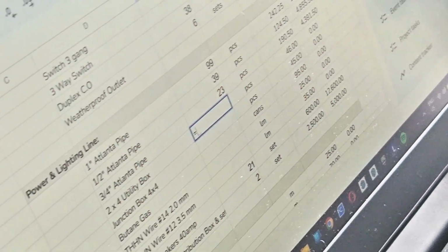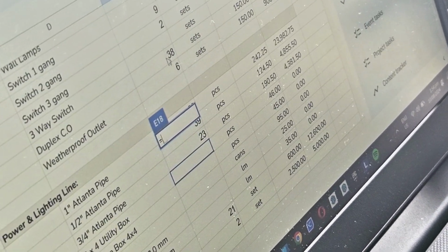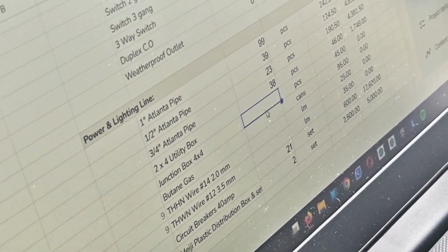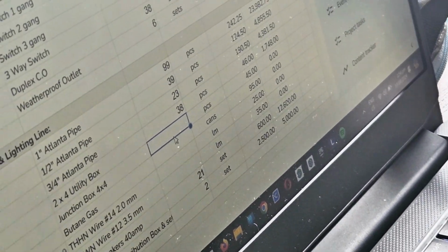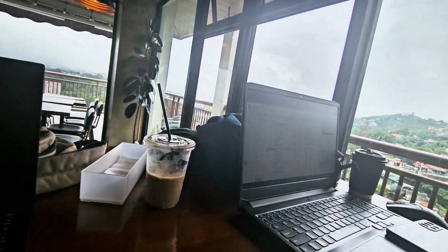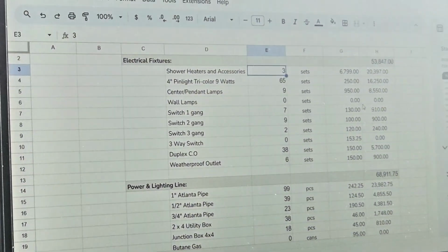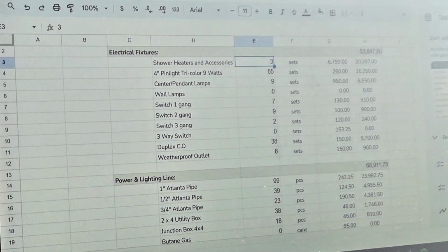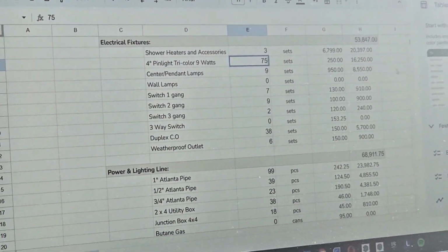And then look for the total number of outlets up there, which looks like CO. There, equal, yes, enter. As you need. But even your switches actually need a utility box. So plus number of switches. So you can assume 1 or 2 junction boxes per area. Center and pendant lamps, those are anything that's hanging or special lighting. You also need to add the center lamp of the sala. Just in case they won't buy a chandelier, we still have an extra light to put there.